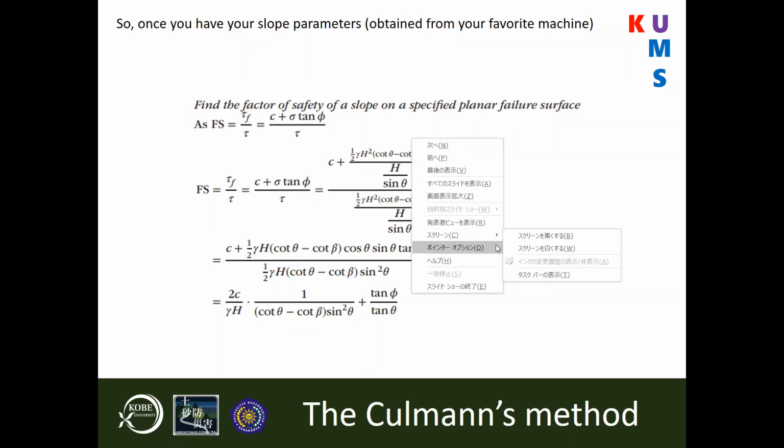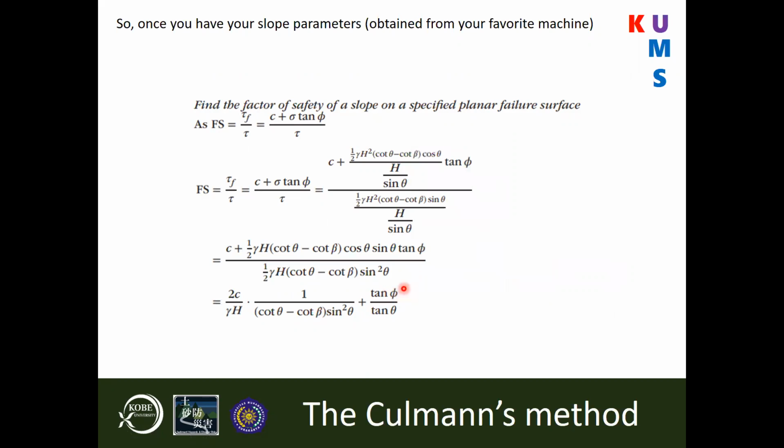You have your phi angle, which is right there, which is, again, your internal friction angle. So this you have. If we think about the previous exercise, that was 30 degrees, right? Here you have tan theta. Theta, you have it as well. If we think about the previous exercise, that was 35 degrees. That was the angle of the slope. Theta, we have it here, same. Beta, we didn't have it the first time, but it's that extra angle we get this time, so you can calculate it.